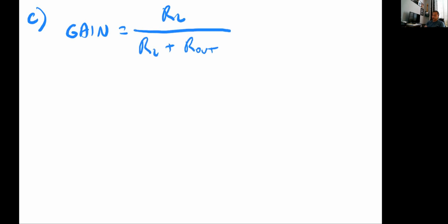And remember that this is a power amplifier, so we're aiming for an overall voltage gain of 1. What we're going to be providing is current to the load. So the voltage gain is going to be close to 1, but it's going to be degraded by the relationship of the load and R out. There's nothing you can do about that with this topology.